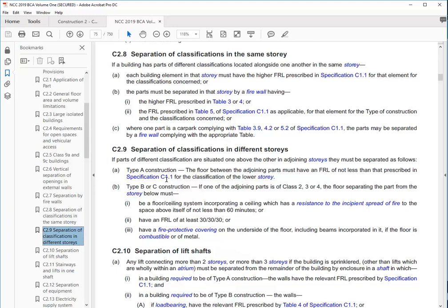Oh yeah, CLT, but they can't do the shafts. I thought they still had to do the shafts with masonry. I'm pretty sure. Because I had a look on the CLT on the Wood Solutions, and they said that... yeah. So anyhow, if you look it up, you might find something different, but I did have a look on Wood Solutions pretty recently to see if there was any way of doing timber shafts, and they said that you can do the floors, but the walls still need to be masonry, and they haven't got a fire-rated timber solution. Hopefully in the future.